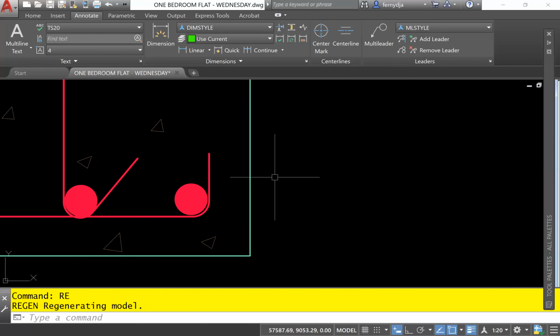If every time you pan and zoom the software had to keep refreshing the screen, then the software would be using up a lot of your RAM or graphics card resources, and then it would slow down. So from time to time, you will zoom in on some objects and see that it looks like it's not a circle. It looks like a polygon with sides. It is not. It's just a display issue. If you were to print it, you would still see it as smooth as ever.